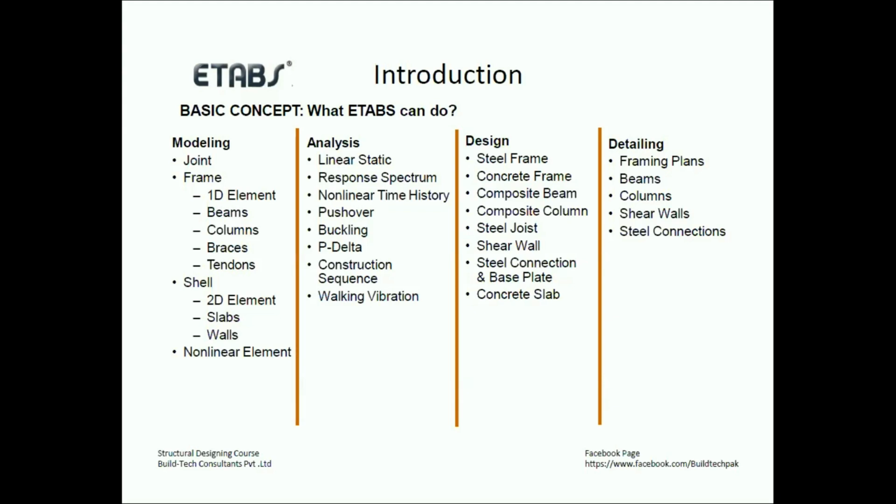They will not understand until you provide a drawing showing a longitudinal section, cross section, the dimensions of the beam, how many bars are placed in the bottom, how many in the top, and what the stirrup spacing is. All this comes under detailing.